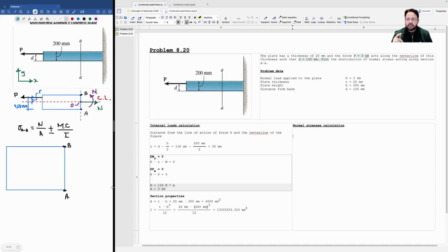So now, because of the normal force, we're going to have a normal stress that corresponds to this part here. How that normal stress distribution looks in the figure, let me just move this one like this. Let's put it in the back here. I'm going to have this shape like this. Oh, this is ugly. Let me try to do it in one go. Better. So this is going to be the distribution of normal stresses due to my normal force, N, something like this. And it's in traction, and we can agree on that. And this is the part that says, this is N divided by A.